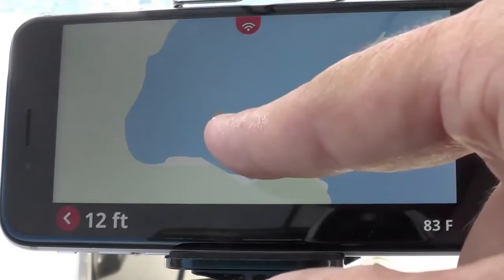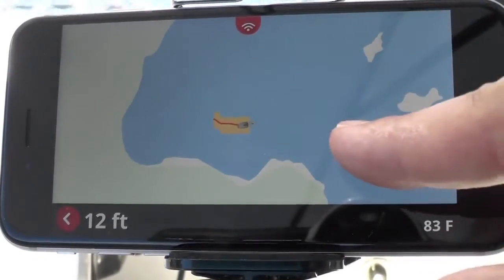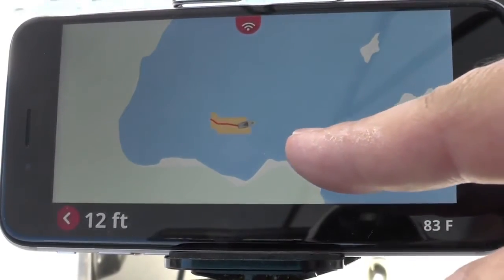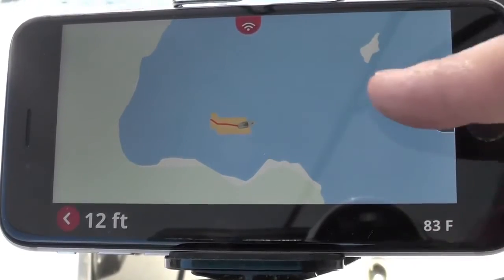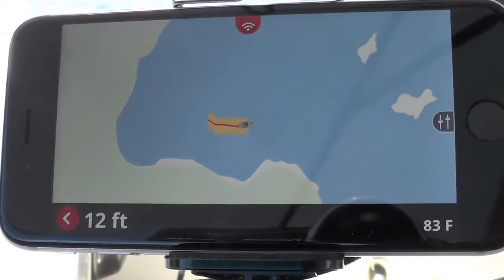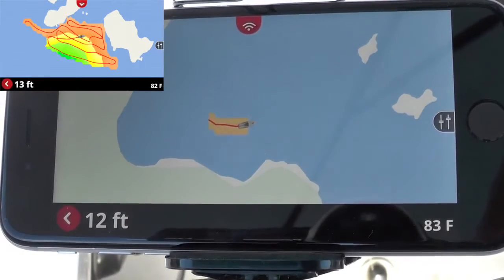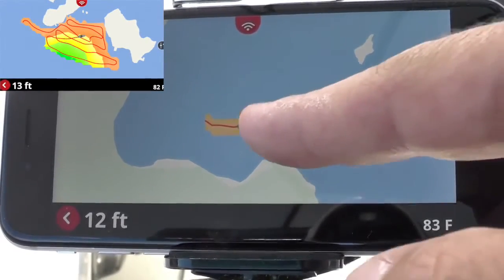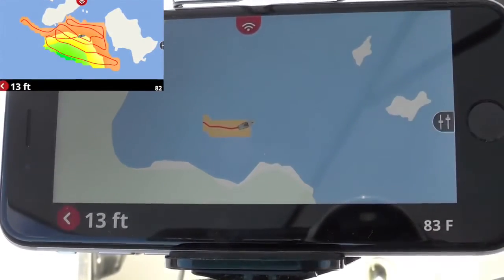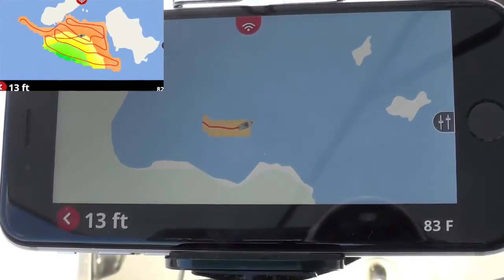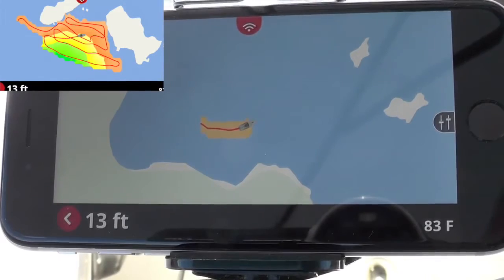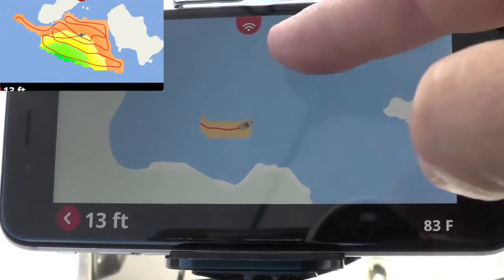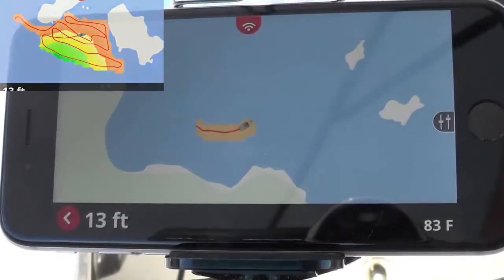So what I'm going to want to do, as I map this area here, is go out, then take another turn and go back. And you'll clearly see as you start doing this yourself that you want to space the different passes of the boat across the area that you're mapping in the most efficient manner possible. What you're going to realize as you practice, depending on the speed of your boat and the water you want to survey, is you have to turn and just leave your boat going for a few minutes to get the best possible angle and distance, to make sure you don't make your turns too tight and overlap, and not too big, leaving gaps in the actual map.